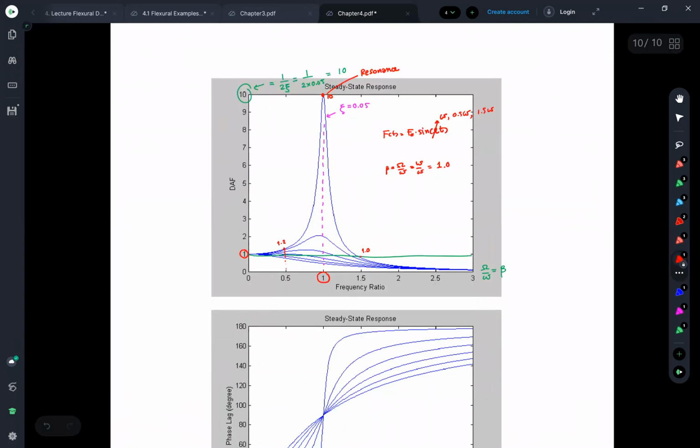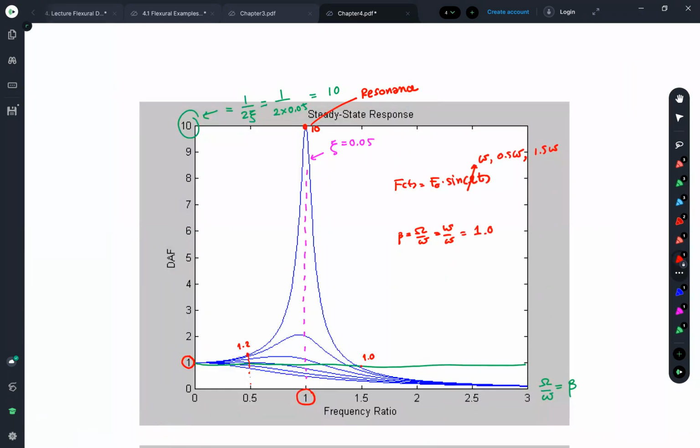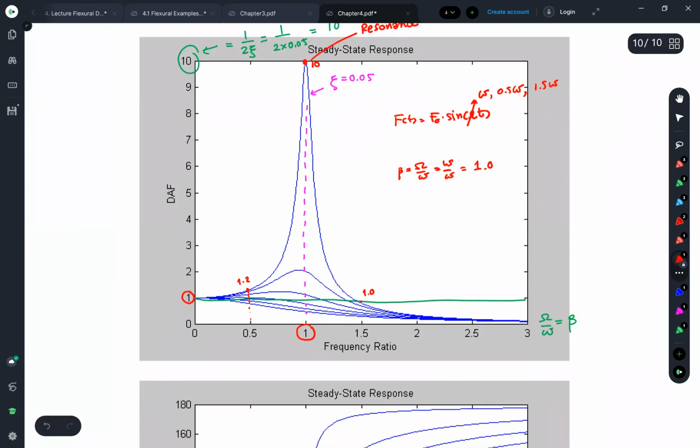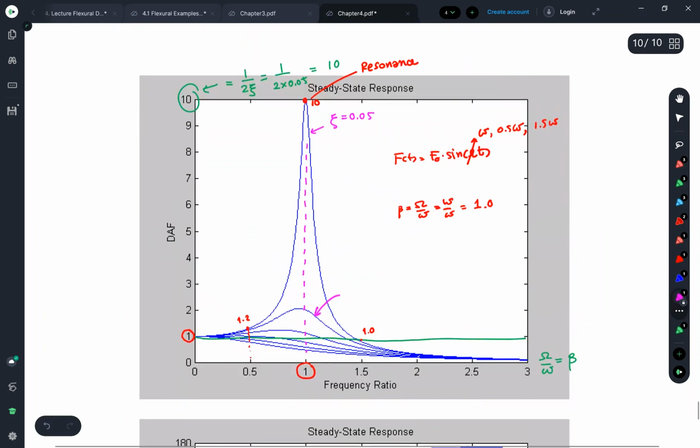With resonance, if we increase the damping ratio, can we decrease resonance? Yes, right. You see the plot here, I haven't explained it to you yet. It's about this one, right? And this one, I think, let me see, 25%. This percent is 0.25.